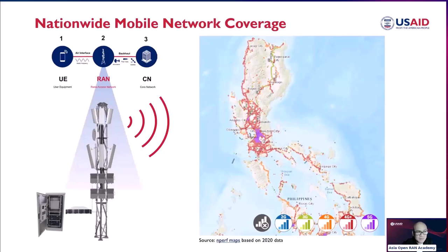Because the output power of this radio access network or cell sites is typically, for example from the radio, 20 watts, 40 watts, or 80 watts in some cases. That's why the coverage is very limited compared to a broadcast station. And the tower height of this radio access network, probably the highest might be 50 meters or 60 meters in height. Very frequently, you can see 100 meters for a cell site. Unlike the broadcast stations, which you can see around 100 meters and then transmitting at a higher power rate.